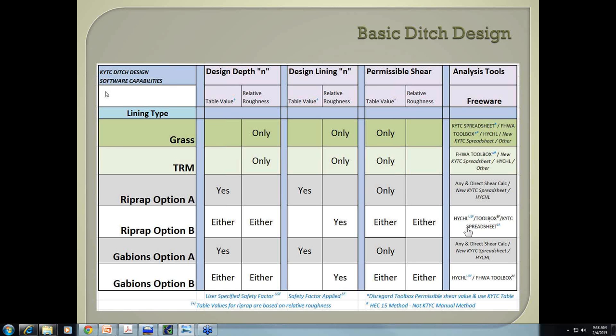But technically, according to HEC 15, both old and new versions, the trigger is at 200,000 for the particle Reynolds number, and below that it's a linear interpolation to get the appropriate shields parameter. I just wanted to point that out, as that may be one aspect of what seems, from some designers' perspective, to be a change in the design approach or the allowables.